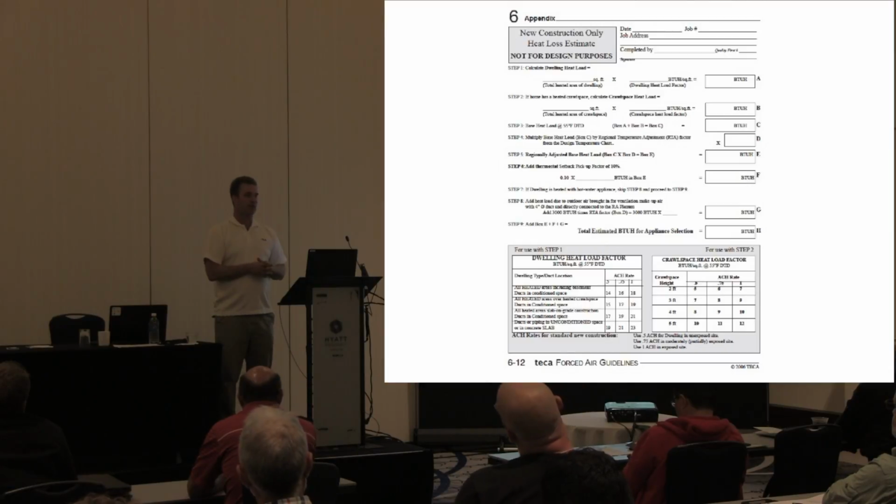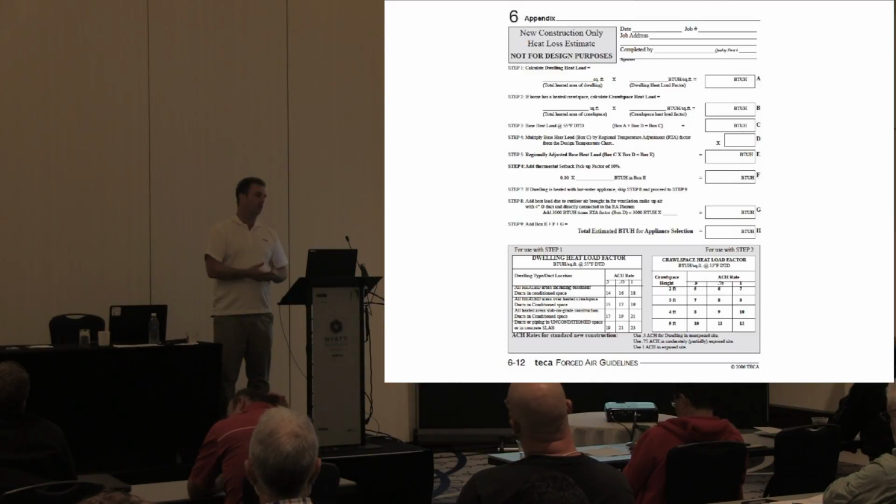Or, I don't know, this is a forced air class, but we do hydronics too. Maybe a combination system would be more suitable for those rooms that don't require any cooling, with a floor system or some other kind of hydronic system in those rooms, just with fresh air coming in, or some small vent for fresh air. Then have forced air where you know for sure you need air conditioning, and you can supplement those rooms that might be a little bit cooler because now they have individual control, because radiant's a lot easier to control individually without any issues than forced air would be.